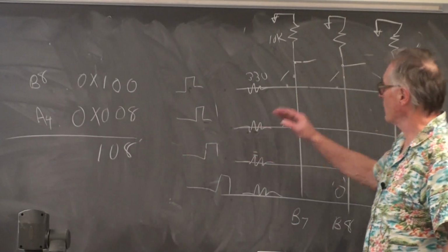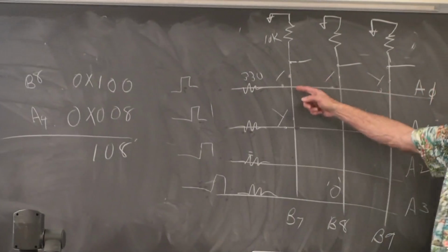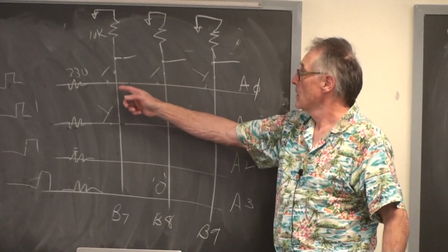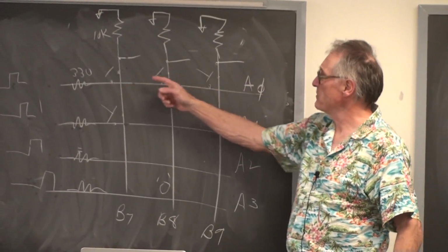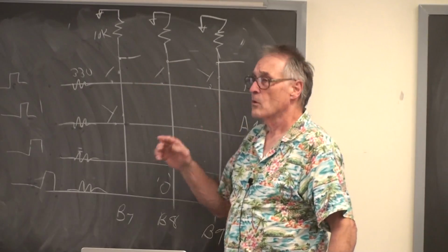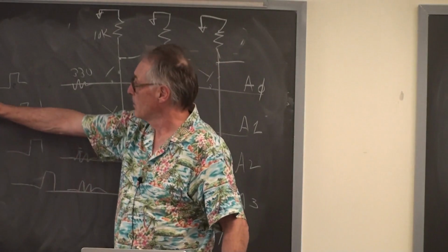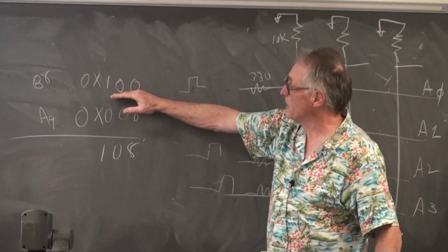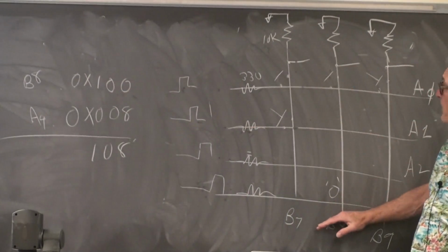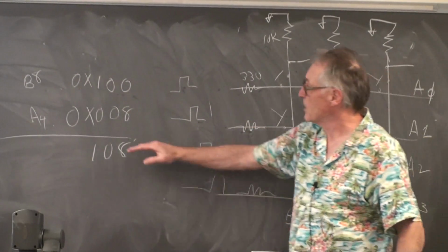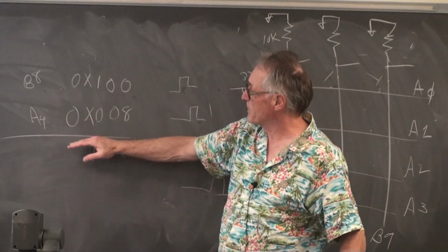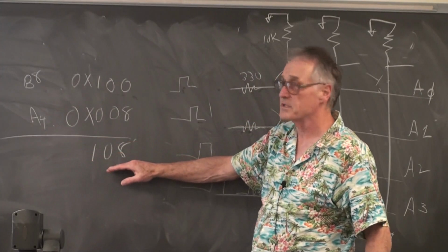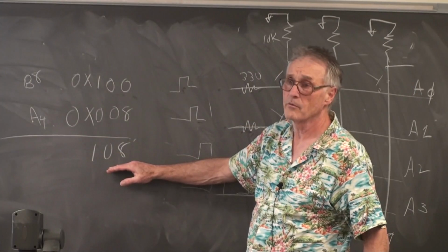So when we detect that one of these 3 bits is non-zero, we OR together the value of the bit pattern in the B register with the value of the bit pattern in the first 4 bits of the A register, the output register, and we have the scan code for the number.